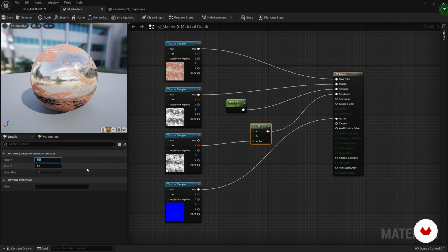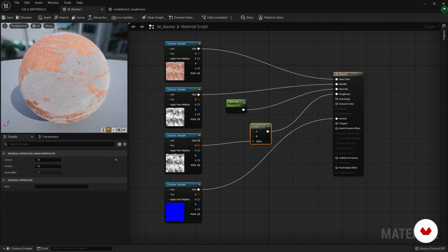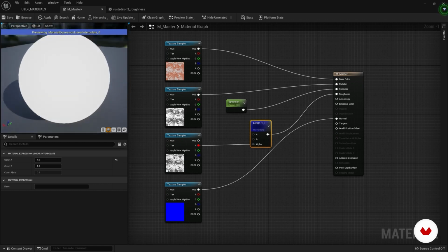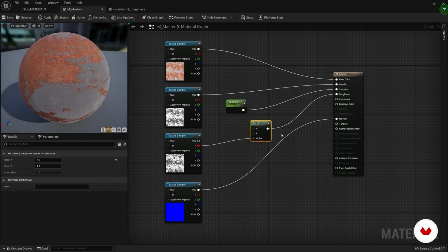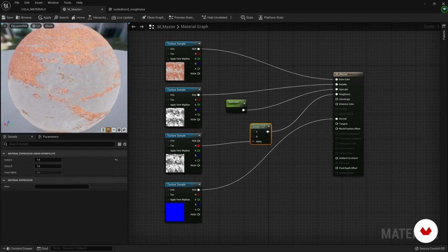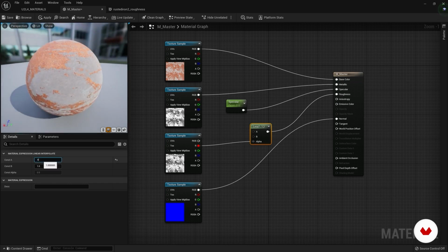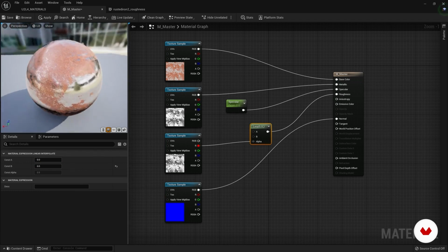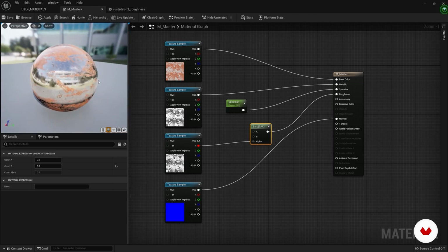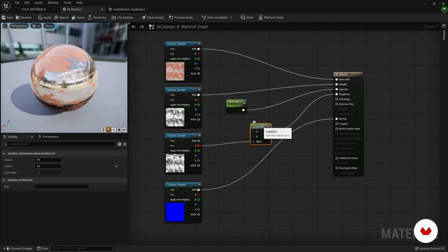By setting a minimum value of 1, it will become all white. You see, everything becomes completely opaque. Let's go see the preview of this node. We stop, then all white for the roughness. It means rough, so it doesn't reflect. Let's do the opposite, 0 and 0. It will all become reflective. What does this allow us to do? It allows us to adjust this parameter.